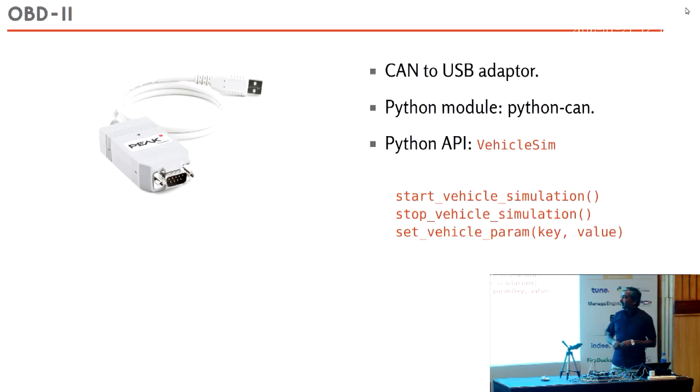And then coming to the OBD interface, we said that there's a CAN bus. Now, of course, the PC does not have a CAN interface. So what we do is we have a USB to CAN adapter that can take these CAN messages and provide them to the PC, or take messages from the PC and then provide them to the device under test. So basically what we're trying to implement is a vehicle simulator. The OBD to the digital cluster connects to a vehicle. We don't have a vehicle over here, so the test PC acts as a vehicle simulator.